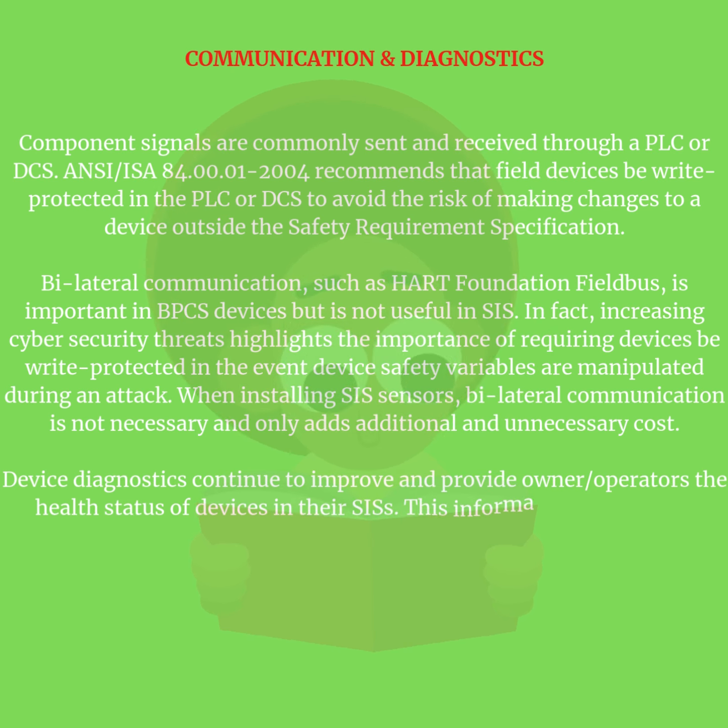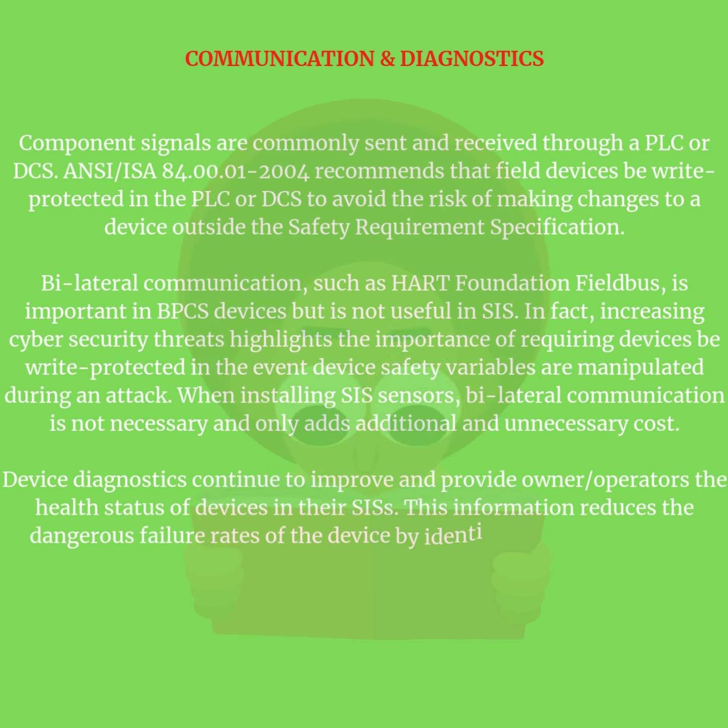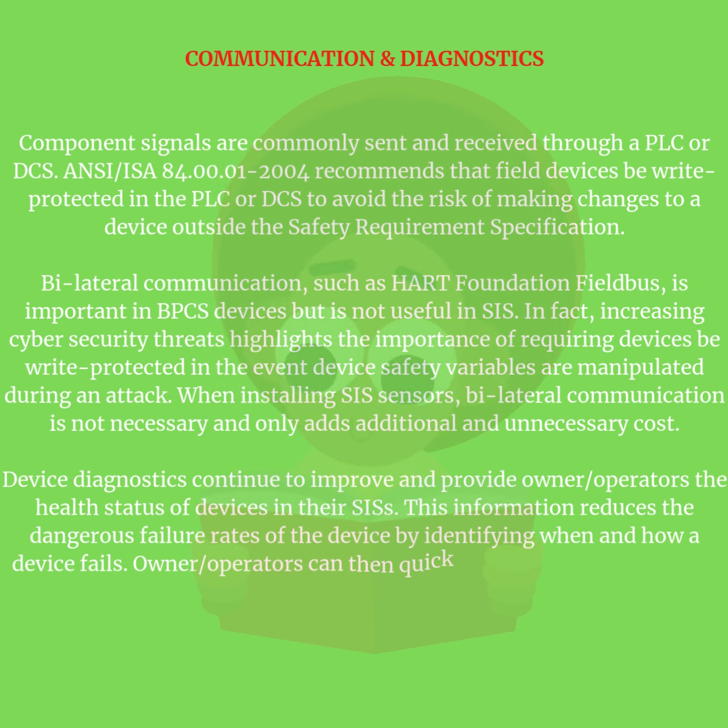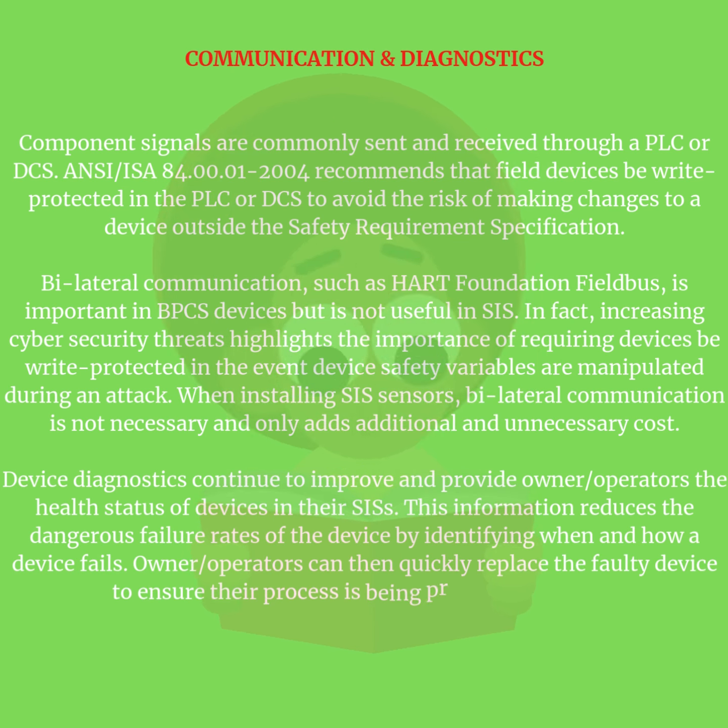Device diagnostics continue to improve and provide owner/operators the health status of devices in their SISs. This information reduces the dangerous failure rates of the device by identifying when and how a device fails. Owners/operators can then quickly replace the faulty device to ensure their process is being properly protected.